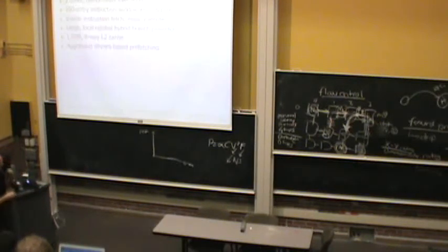And if you look at the core, this employs all of the concepts that we talked about. A lot of out-of-order execution in the core. Well, you cannot read this probably, but these are essentially the issue queues or schedulers and many functional units here. Aggressive branch predictors, and this is the reorder buffer. IBM calls it the global completion table, if you will.